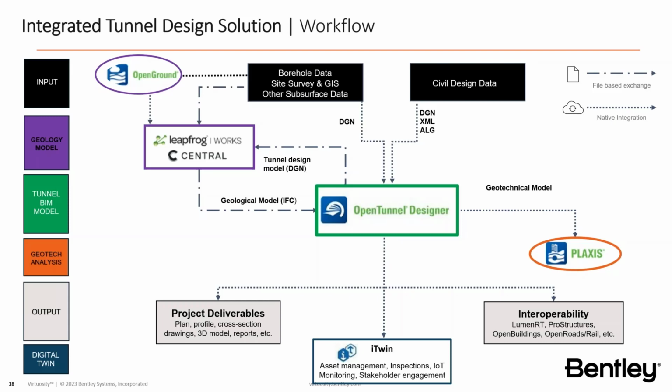OpenTunnel Designer is built over MicroStation and also over OpenRoads Designer. This means that we have the entire civil intelligence that OpenRoads Designer has at this moment on the market. You will be able to create your own alignments inside OpenTunnel Designer, and also you will be able to open OpenRoads files that have been created with corridors and alignments, or you can import the alignment through an XML, ALG, or any other file format that we are supporting.